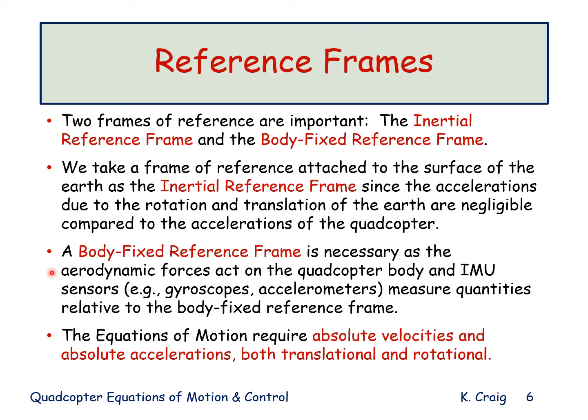A body-fixed reference frame is necessary as the aerodynamic forces act on the quadcopter body, and the inertial measurement unit sensors, the gyroscopes and accelerometers, measure quantities relative to the body-fixed reference frame. The equations of motion require absolute velocities and absolute accelerations, both translational and rotational.